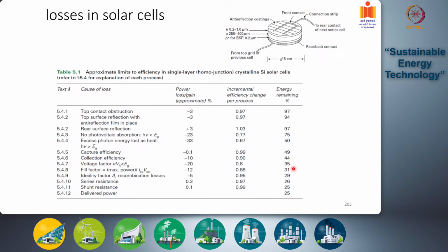So here we have again a large drop to around 35% of energy remaining. Okay. So remember that this is due to the presence of dark current and other currents that are created, which is decreasing the open circuit voltage that is available below the space charge voltage that is actually developed across the PN junction.